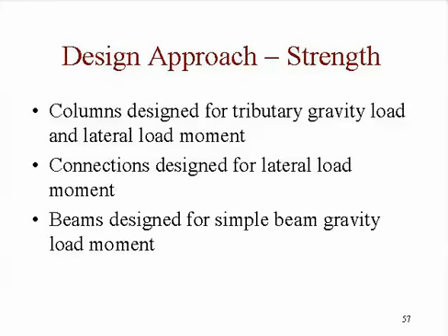Now, how do we design the columns? Well, we can design the columns for tributary area for the gravity load and the lateral load moment that we just calculated based on that distribution. We design the connections for the lateral load moment. And as we've already said, the beams are designed for the gravity load moment.